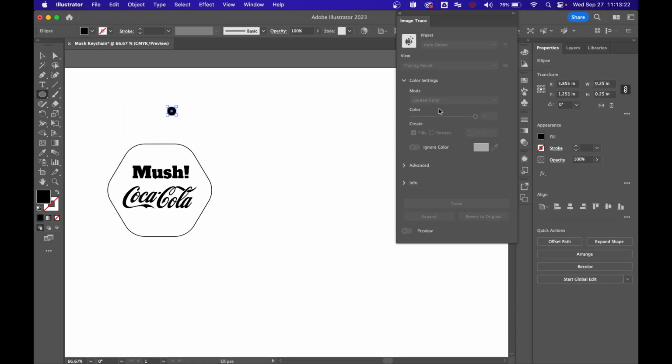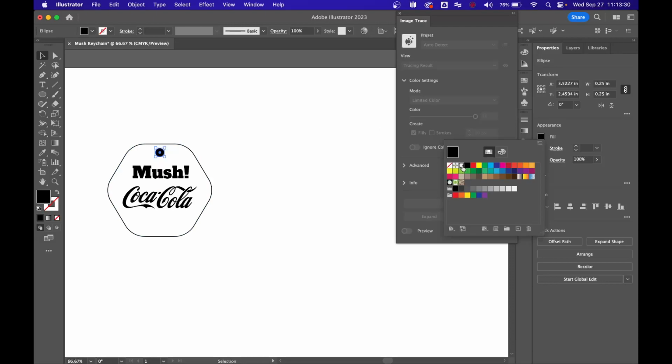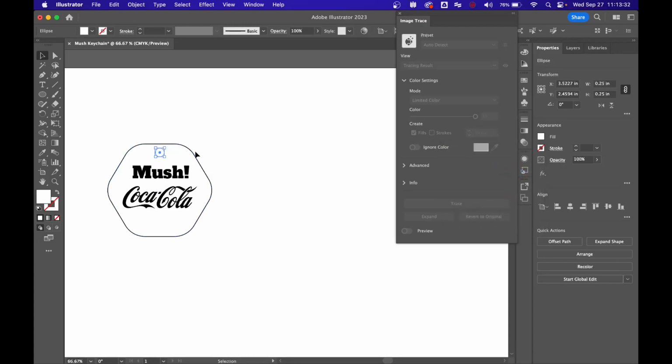And there we go. The last thing I need to do is make sure my vector lines that I want to cut through are the right settings. I give it no fill because I don't need to fill it in there. This one, and I'm holding down Shift, and the outside of the keychain. The stroke needs to be 0.001. Hit enter, and it is there. All right, this one's not there. Do it again, 0.001, and we are good to go.